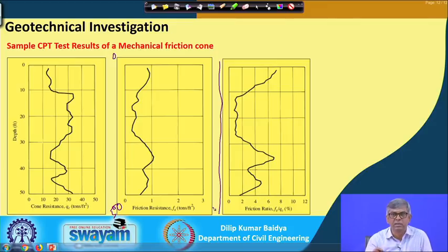So, this is the way we get CPT data, and once you get the data you can see this is the variation. So, it is a continuous variation, then how to find out, at every point, will a different soil be treated like that? No, I can see that this is the average value. So, up to this there is one layer, and up to this is a layer, this must be another layer.